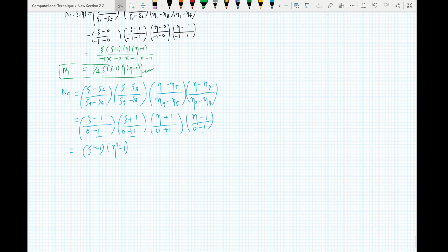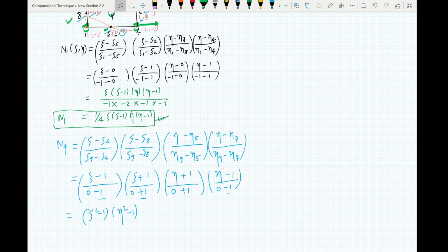Today we learned about shape functions and the ways to obtain them in 2D triangular and rectangular elements having different numbers of nodes. You can have internal nodes and nodes at the boundary of the elements as well. We also looked into Lagrangian polynomials, where you can obtain your shape functions by using their weightage factors.